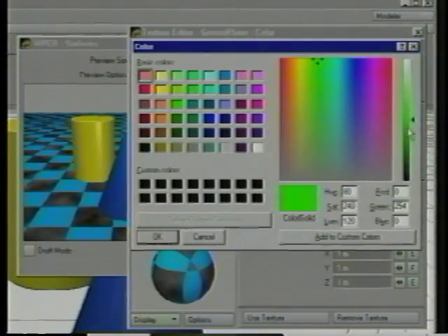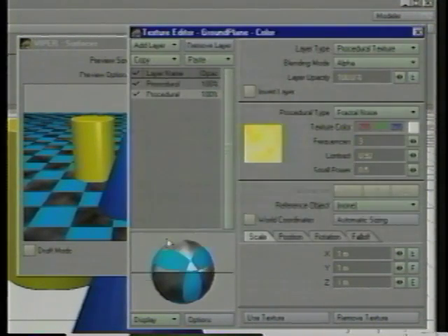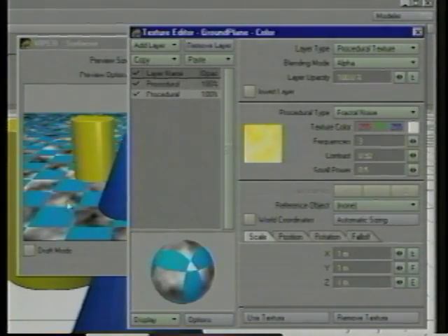And let's go ahead and make it solid white. Okay, so you can see it's subtracting an alpha channel back to the original texture there. This is a real good way if we want to have multiple textures stacked, and we want to cut one texture out of another. You just put one alpha channel in between them. Then you can have like an image map, a checkerboard, and another image map, and then you'd see the two images together composited by that checkerboard.